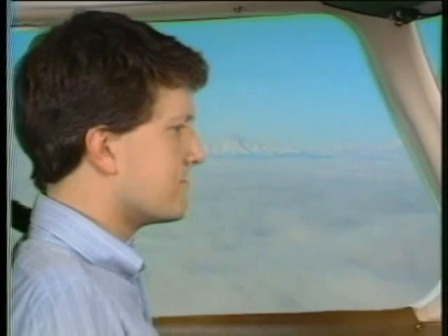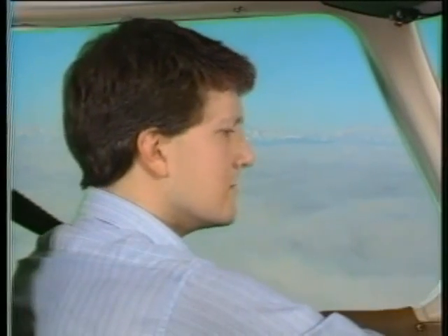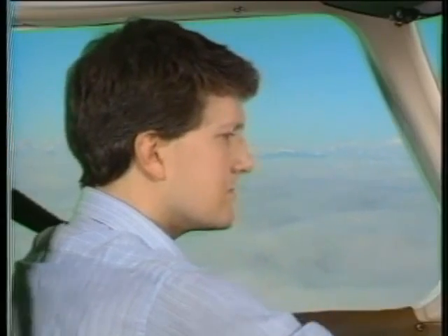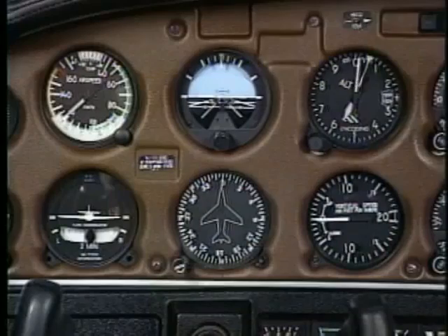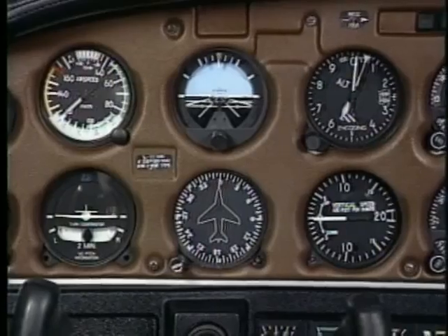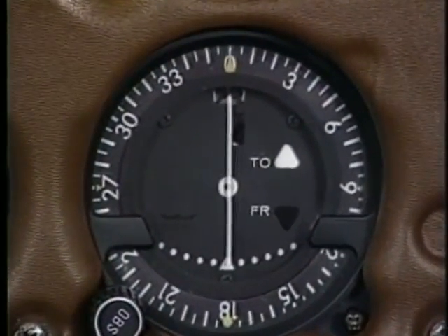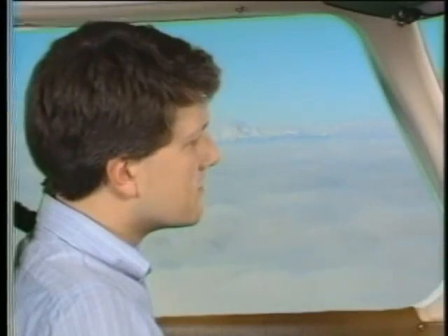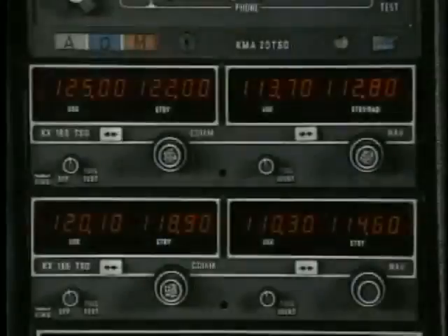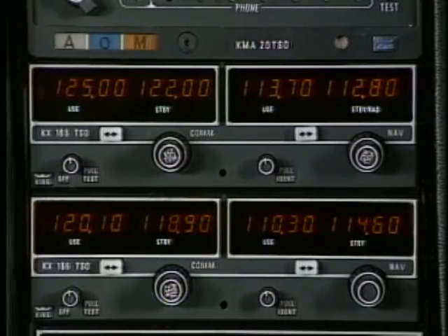The ability to visualize your position is one of the most important IFR skills you can develop. It makes IFR navigation much easier. With that in mind, let's review some of the basics of VOR navigation as they relate to IFR flight. We'll begin with this clearance from departure control. Warrior 312, 5 miles northeast of Jackson VOR, intercept Victor 77 and resume your own navigation.